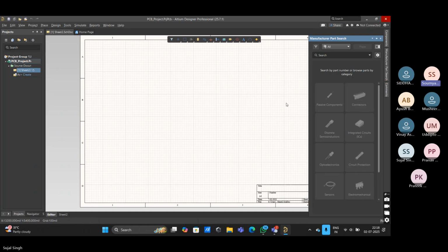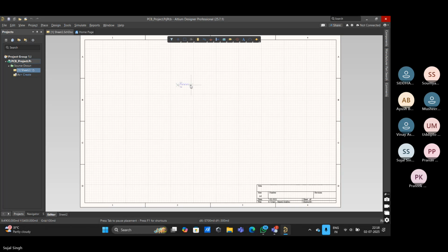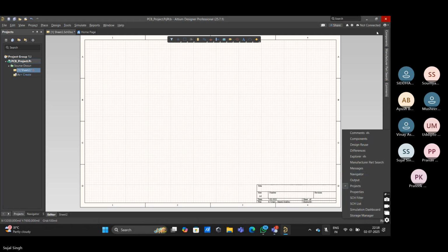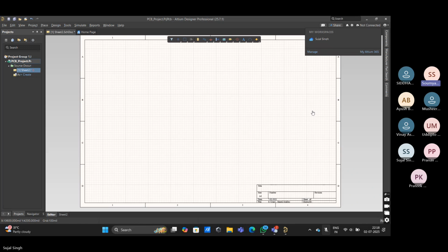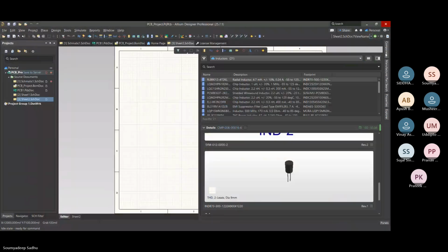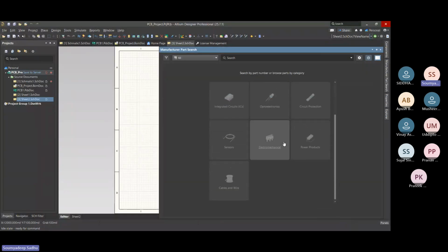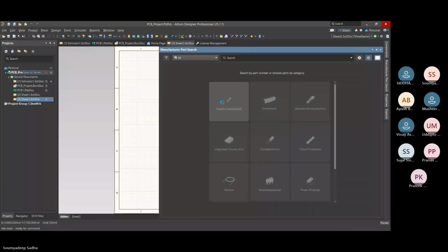Okay, just use the substitute, the manufacturer part search, for now. Okay, I can use a general part, like an inductor, from the components. If there is no model for it, you can't do PCB design for manufacturing, because you don't have the exact inductance value and details. I am taking the charge again. So basically, I will be using manufacturer part for this. It's a passive component, right?